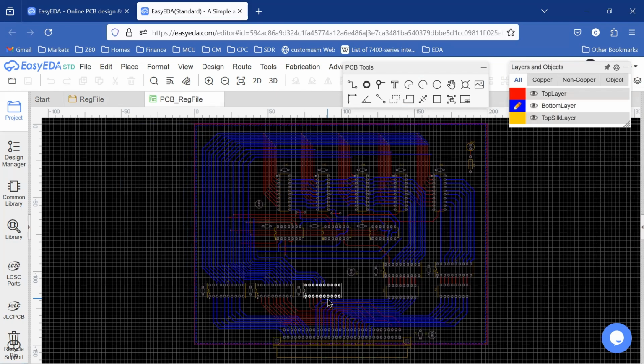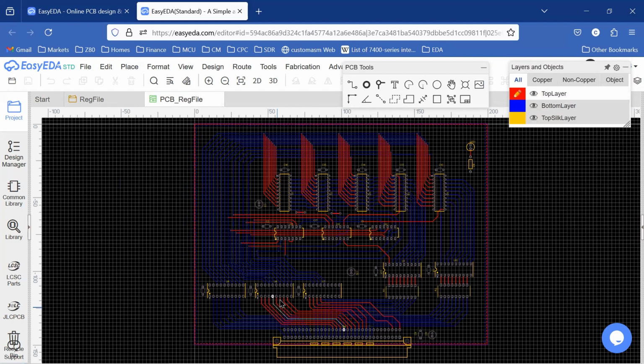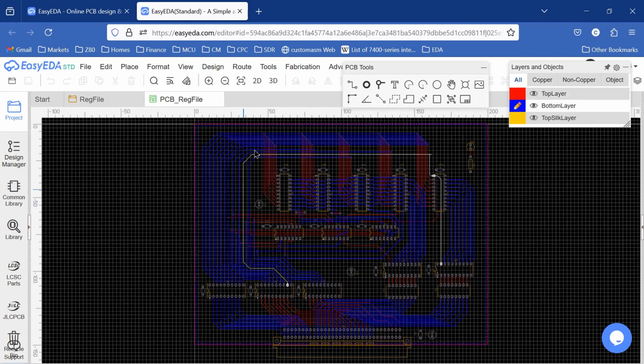Okay, and then we have some of our input lines routed on the top. We have these 2, which are control. The control signals come through here. They're routed from the top off of the card edge, but then they are pulled up and around as the data bus lines were. And so to look at the rest of our major routing on the bottom, our inputs come up above and they're pulled down to our register ICs.